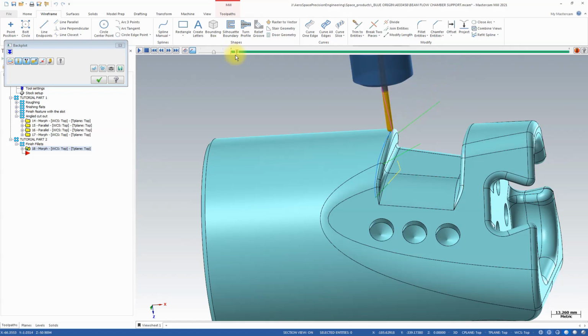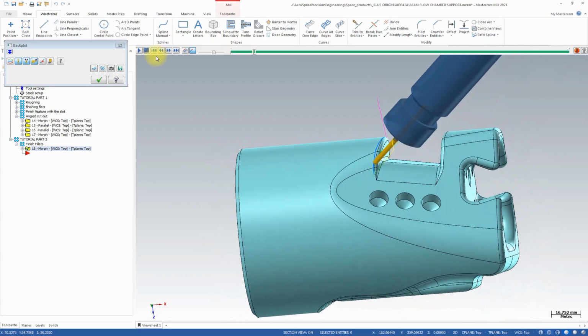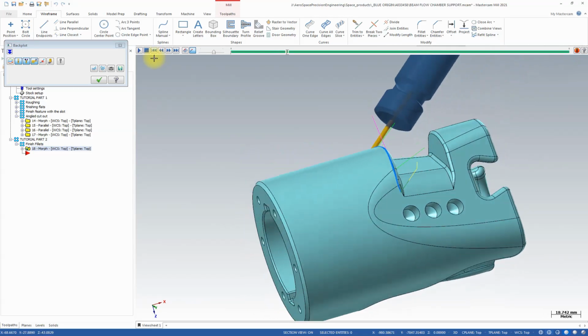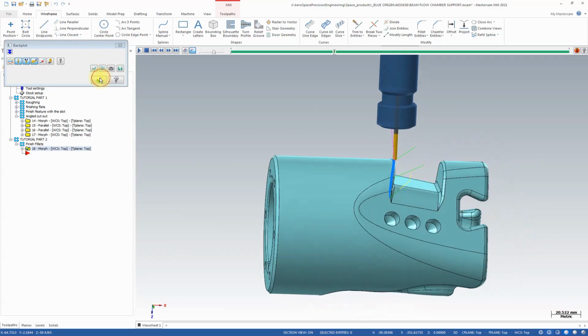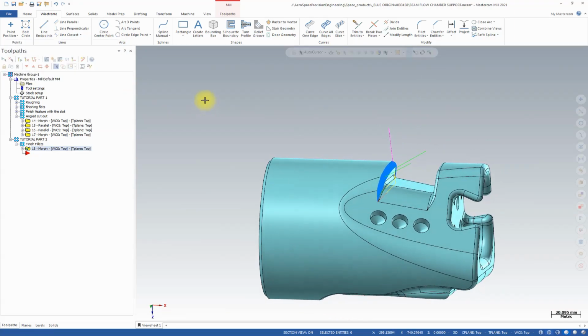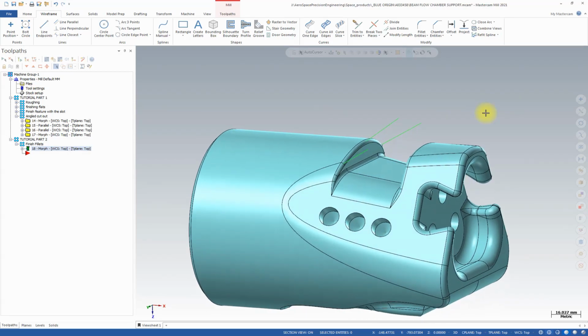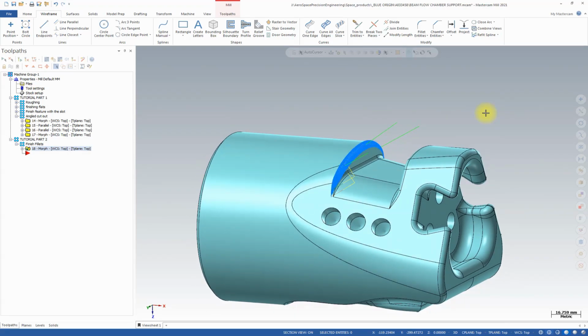Of course, the line that you adjust needs to be one of your tilt lines that you selected in your tool axis control. So as you see, even when you have your toolpath ready, it's easy to adjust the tilt along the cut. Okay, I'm going to undo my adjustment, and that's cool.